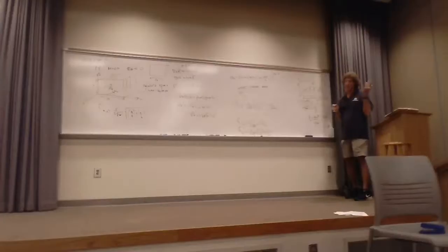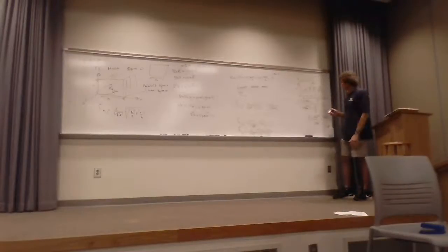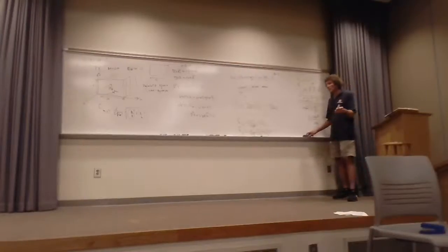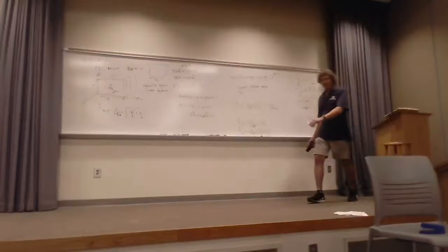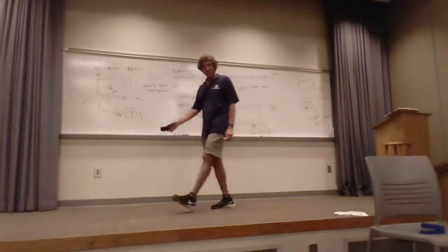I can figure out where I need to be frequency-wise to operate. When you see guides that have millimeter height and width, now you're talking about 80, 90 gigahertz, maybe more. Okay. Trying to give you some insight. So that's how you get the frequency of operation of the lowest mode for a rectangular guide, the most common guides. Are you with me so far?